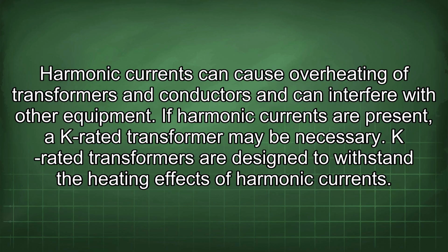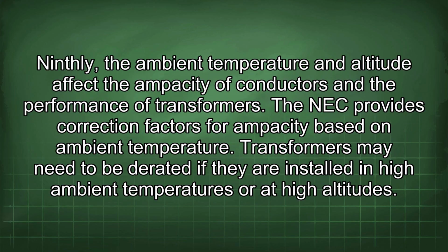K-rated transformers are designed to withstand the heating effects of harmonic currents. Ninthly, the ambient temperature and altitude affect the ampacity of conductors and the performance of transformers. The NEC provides correction factors for ampacity based on ambient temperature. Transformers may need to be derated if they are installed in high ambient temperatures or at high altitudes.